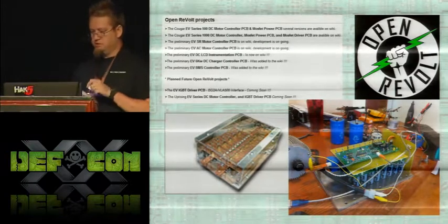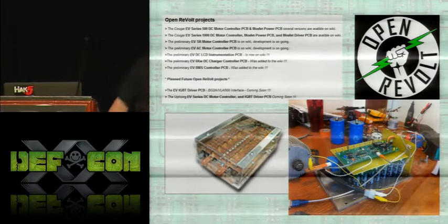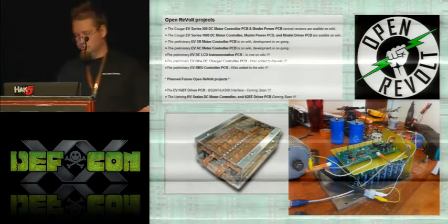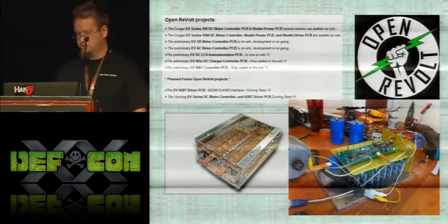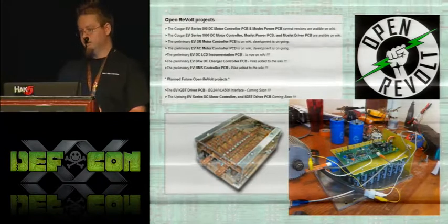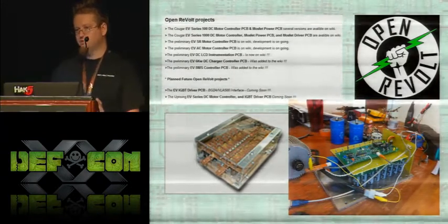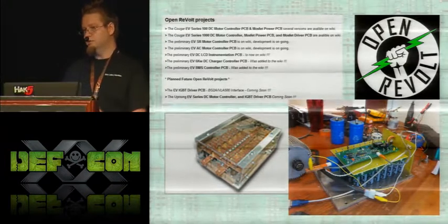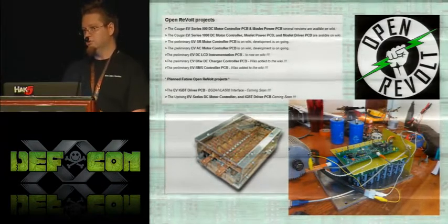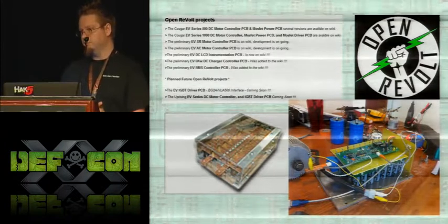They started out with DC motor controllers. They're also working on AC options. So there's all kinds of great stuff you can do there. Plus, it's just really cool to mess with all that electronics. And the best thing about having a do-it-yourself controller is everything's customizable. With my car, I have a 120-volt charger. I have a 120-volt controller. If I want to upgrade to 144 volts, I have to replace both of those.